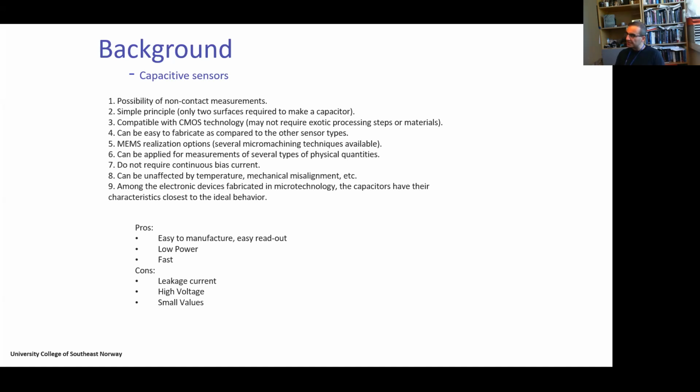I don't want to go into that discussion, but for the capacitor, it's easier. The process which is most challenging is the doping process, because you want to make some materials conducting, and sometimes that is not needed in the capacitive method. Depends on how you do it, but if you have two metal layers or silicon which is already doped, then you don't need the doping to make the capacitor. So you can make them by MEMS, in micro sizes.